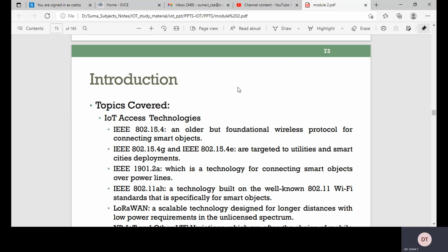There are some criticisms of IEEE 802.15.4 that often focus on its MAC reliability, unbounded latency, and susceptibility to interference and multipath fading. The negatives around reliability and latency often have to do with collisions in multiple access, that is the CSMA/CA algorithm, an access method in which devices listen to make sure other devices are not transmitting before starting their own transmission.